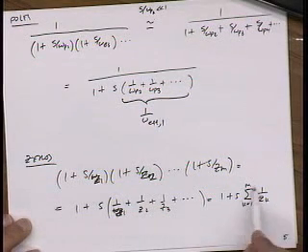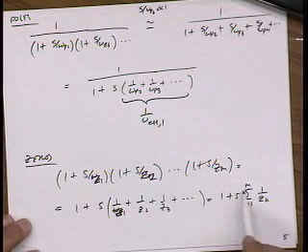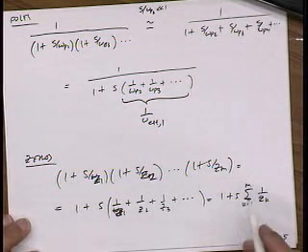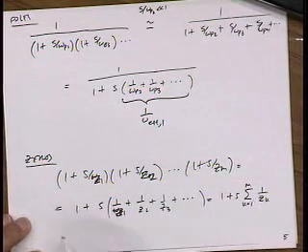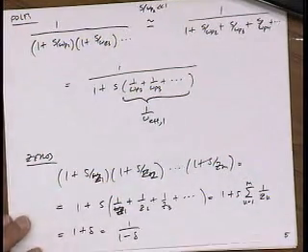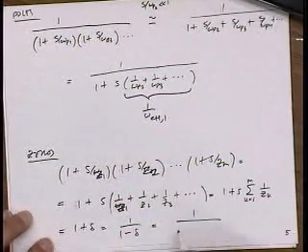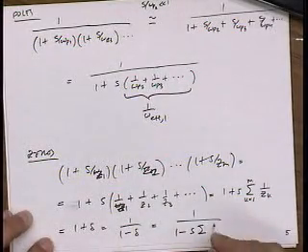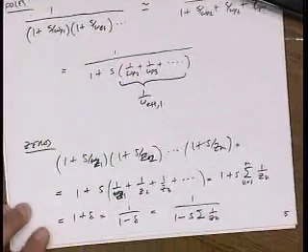And again, if the combined zero is still at a much higher frequency than the frequency that I care about, then this is like 1 plus delta, which I can write as 1 over 1 minus delta, right? And so this looks like 1 minus s times the sum of 1 over zk.